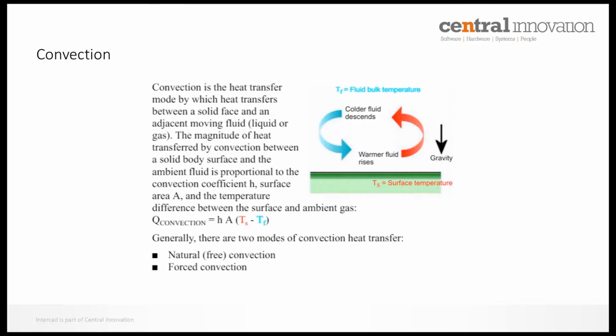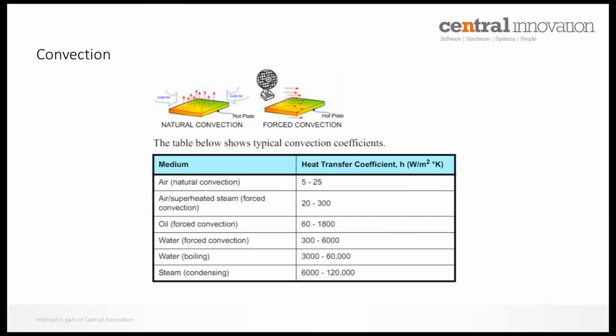So the SolidWorks Simulation Professional module uses the finite element technique, and you can simply study solid bodies with different material properties, but it does not take into account the fluid motion. Therefore, these natural convection currents cannot be simulated during the Simulation Professional setup. Basically, you have to make use of the Flow Simulation module to understand the behavior of air currents or fluid currents, but still the effect of natural convection can be taken into account by using a heat transfer coefficient. Later I'll be explaining how to decide what value to use and how to approximate it. The second type of convection is forced convection.